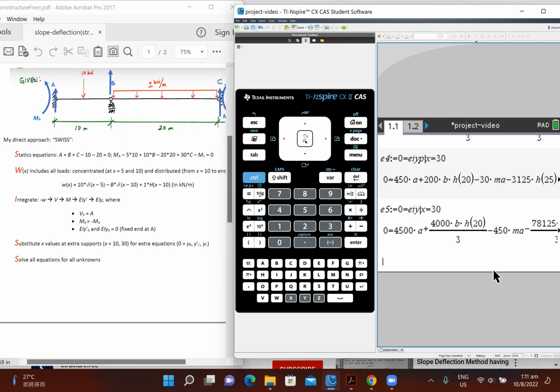simplify by defining the step function now. I did not define that earlier because I need h to be symbolic in order for my integration program to work. But now I don't need to integrate anymore. So I'm going to define my step function explicitly using the internal when function. When x is smaller than 0, then return a 0. Otherwise, give me a 1 when the step function has a positive argument.